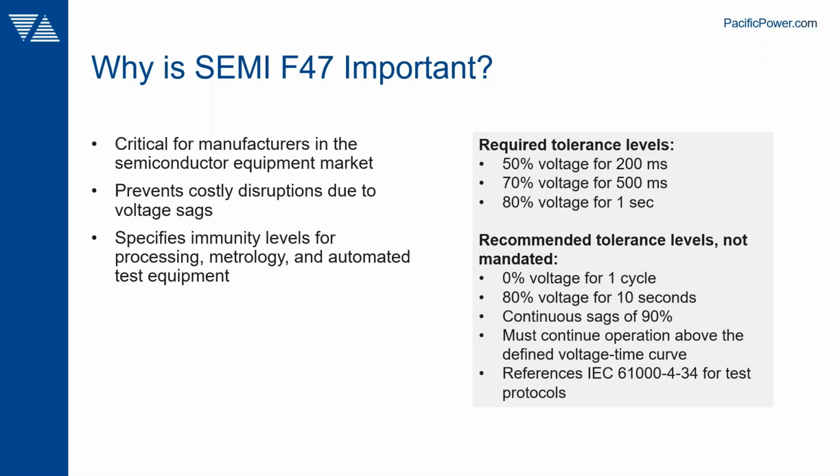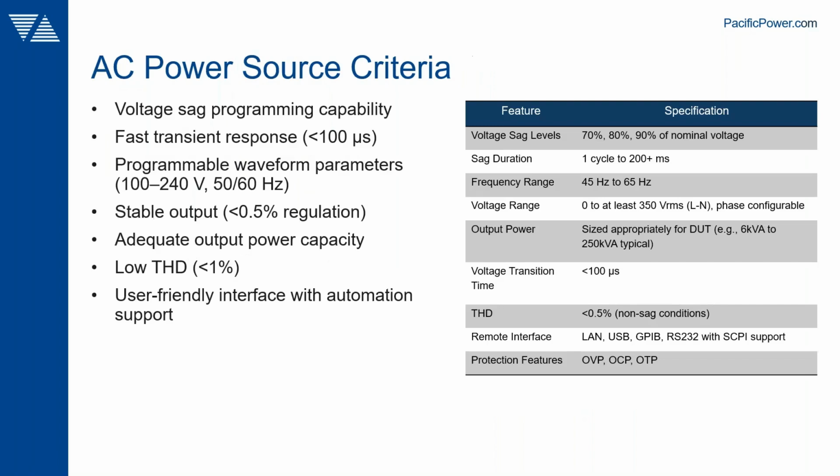So a lot of manufacturers of this equipment will try to do their testing in-house, and that requires a programmable AC source or grid simulator. You can obviously program the sequences manually, but with the test sequence it's much easier to do. It's already pre-written, and it also generates a test report at the end. All these dips and interrupts can be selected from the test sequence and executed once or repeatedly as needed to validate and verify your equipment has the proper ride-through capabilities.